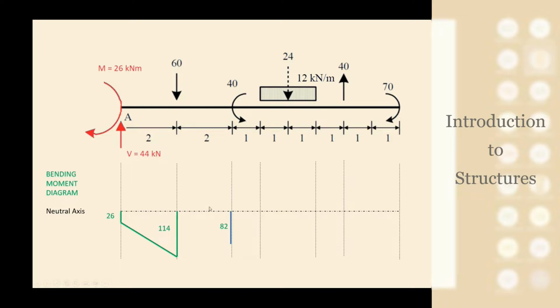And between forces, again, the variation of this moment will be linear. But before drawing the variation in the interval, we are going to calculate the moment immediately after the applied moment. So now we are in this cross section immediately after the moment, 40 kilonewton meters. So the moment here will be 44 times 4 plus 26 minus 60 times 2 minus 40, the moment that is now included in the cross section I am analyzing. And for this reason, the moment immediately after is 42.